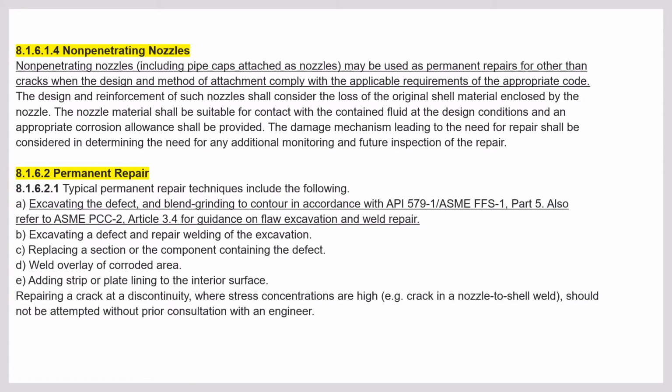Non-penetrating nozzles. Non-penetrating nozzles means it is not through. Okay, non-penetrating nozzles including pipe caps attached as nozzles may be used as permanent repair for other than cracks when the design and method of attachment comply with the applicable requirements of the appropriate codes. So the design and reinforcement of such nozzles shall consider the loss of original shell material enclosed by the nozzle. So this is one of the repair methods, like lap weld, like fillet patch welding. This is the non-penetrating nozzle. It is one of the repair methods.